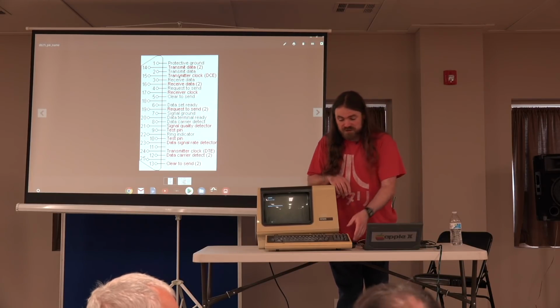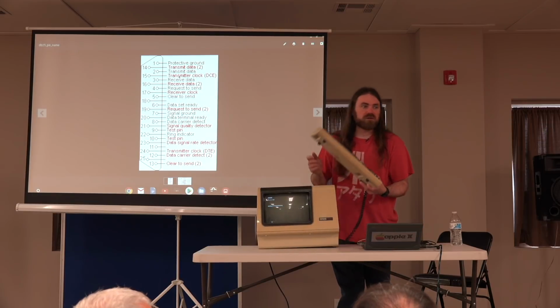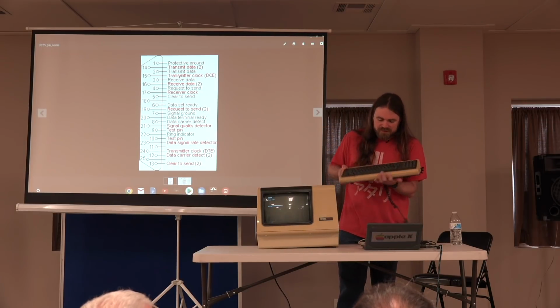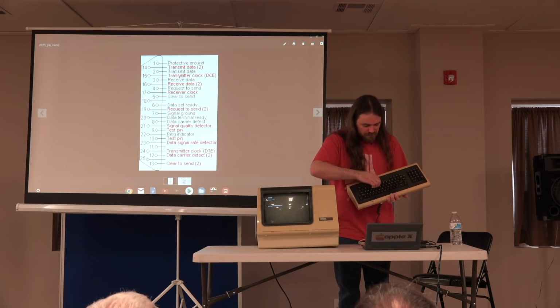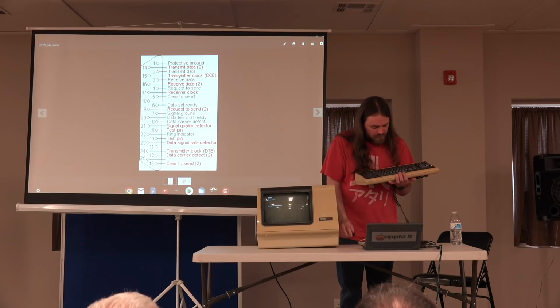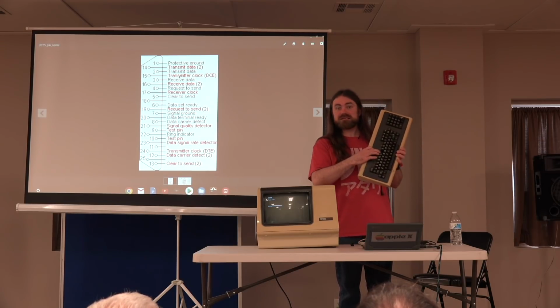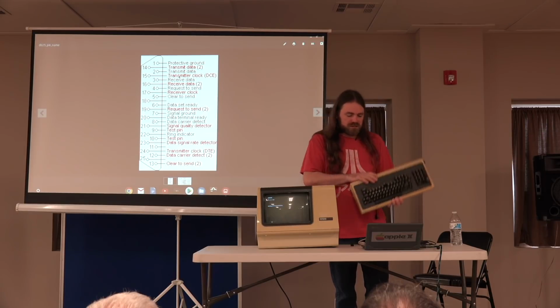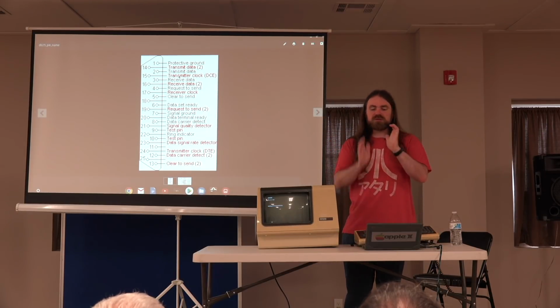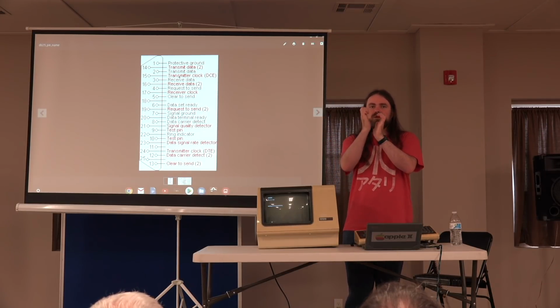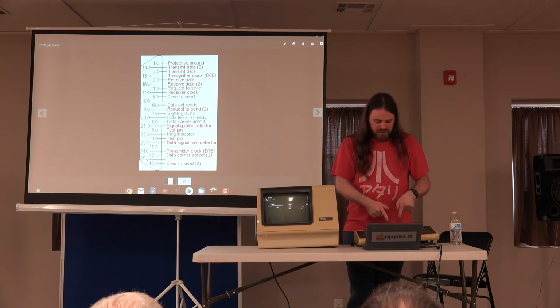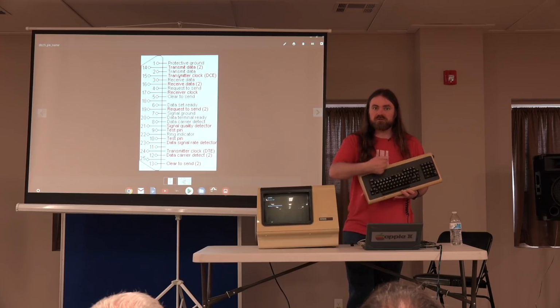Okay, yeah, key switches are becoming a failure point. This type of keyboard uses these little spring contacts. You can't see, obviously, because you're too far away, but there are little fingers on one side and a flat thing on the other with a bar in the middle and a spring, and whenever you press the switch down, those close. The contacts are exposed. You can see them right here from the top.